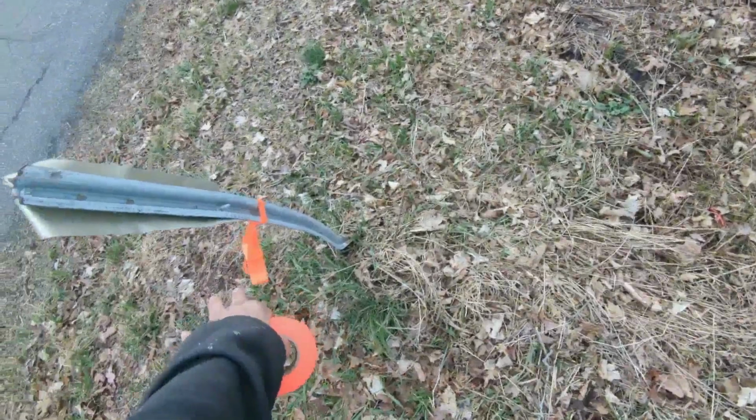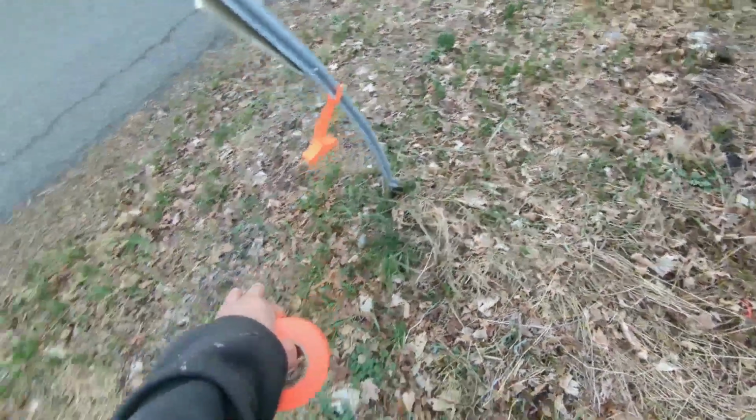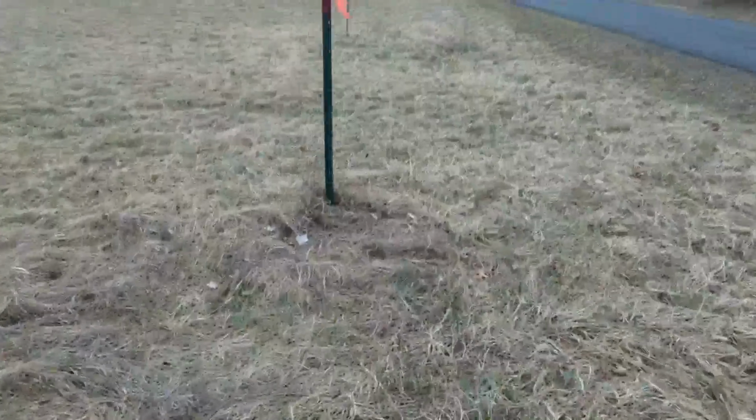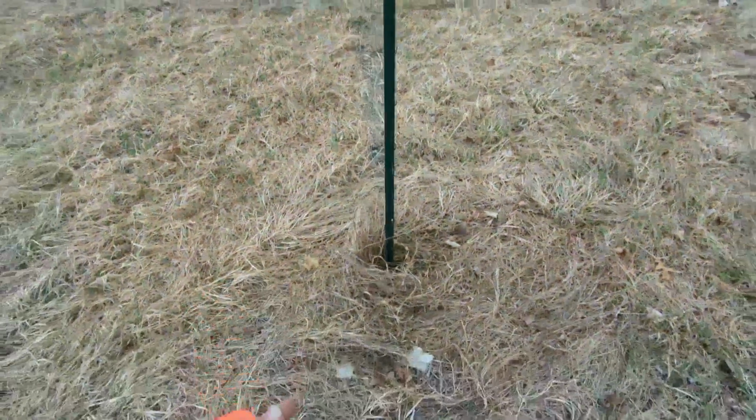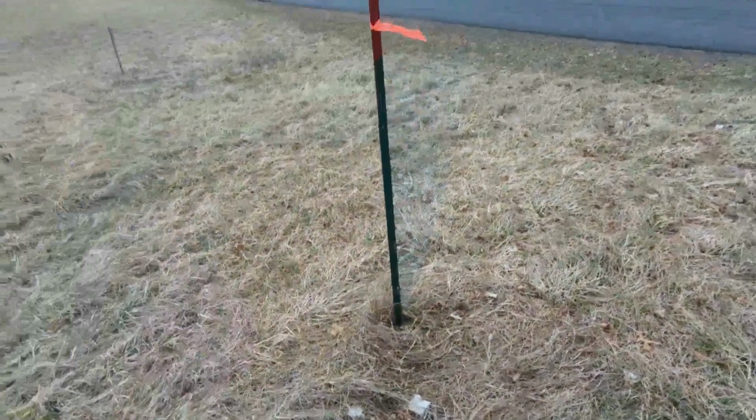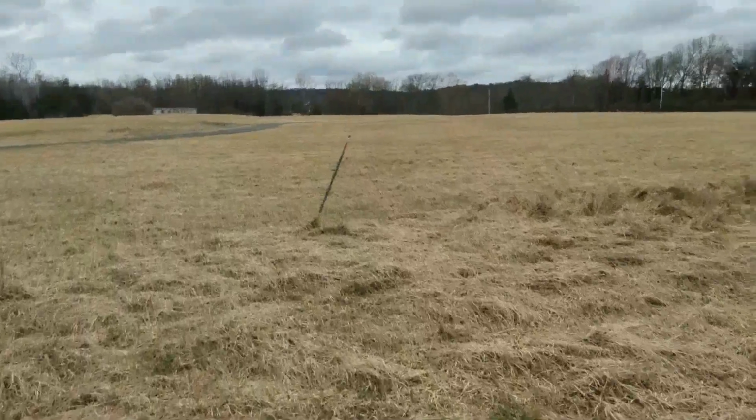So I flagged it for reference to make it easily findable, because we're doing this survey through aerial drone photography, and it's going to be a little harder to spot precise points with this type of technology, I think, compared to what I'm used to, which is total station, or GPS, which is ground-based robotics, and this is aerial-based. So this is the other corner post in the front, and we'll go back through and flag up the outside edges. I will not flag the split lot division.